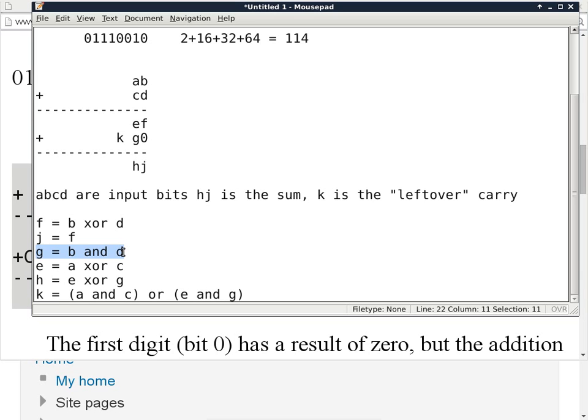In that picture, these wires have no particular label. Since we go up there for the initial half adders, that C is just the carry of the half adder's inputs. So the top one is the carry of A and C, which is the top input to the OR. Then the bottom one is the carry from E and G. Correct. Yes.